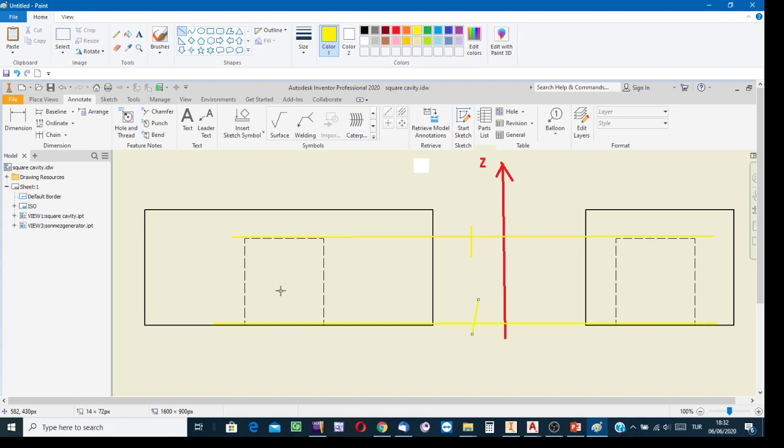On the front view, it is at the inside. On the left side, it is at the inside. So it is obvious that this hidden entity is an interior feature, not an outer feature. So it cannot be a solid extension. It must be an empty space.